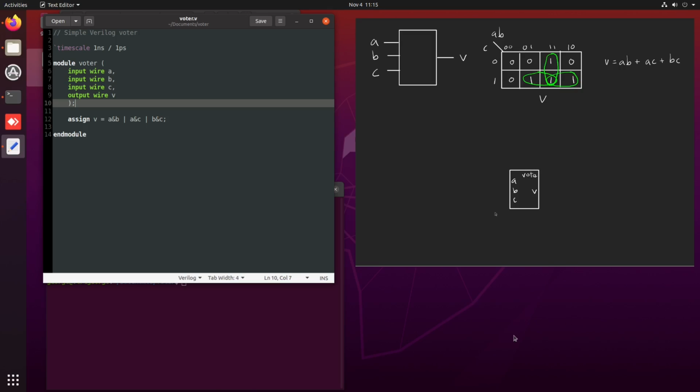Okay, so that's a Verilog description where we are going to put one instance of my voter circuit. Normally, I will call this instance UUT, from unit under test. In that new Verilog description, I will put a copy of the voter and then connect it to signals that generate input values that I will apply to the inputs.